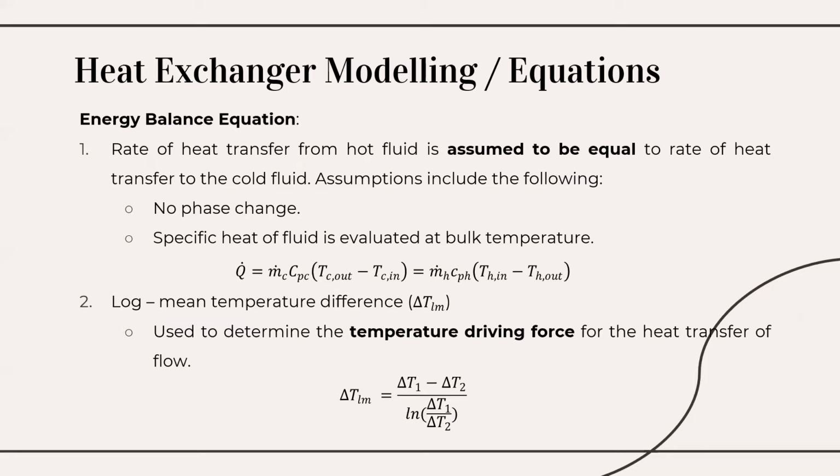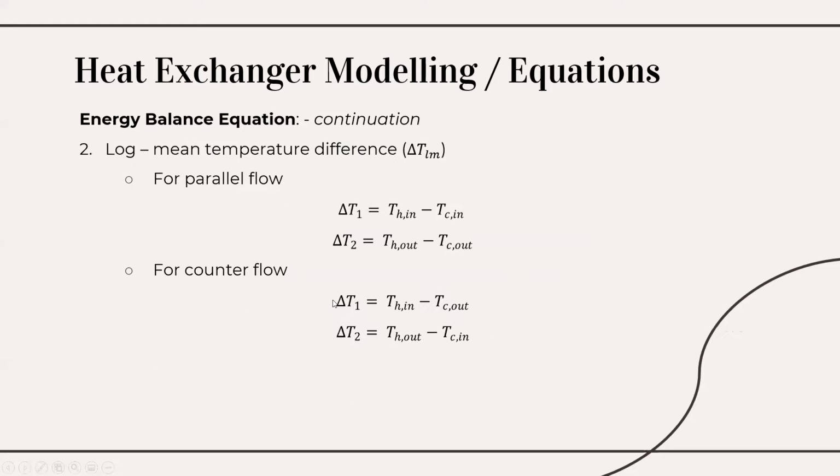Second is the log mean temperature difference, which is used to determine the temperature driving force for the heat transfer of flow. The computation varies depending on the flow configuration. The general expression for the log mean temperature difference, or LMTD, is shown below. Here is the difference in the calculation of temperature difference 1 and 2 if the flow is either parallel or counterflow.